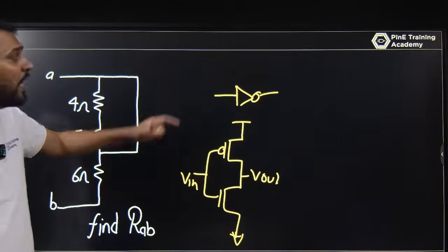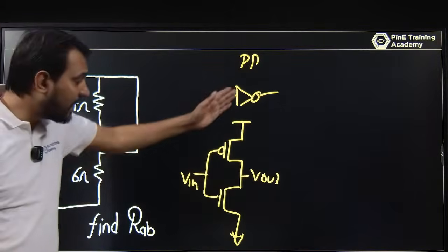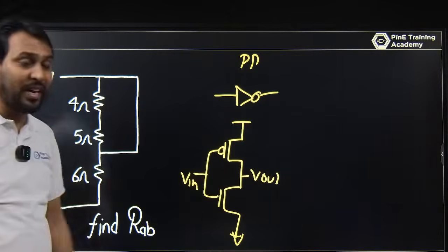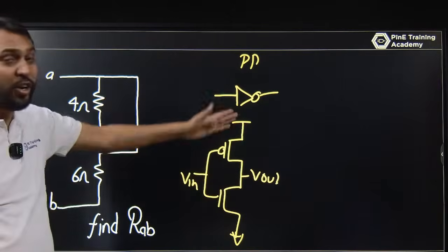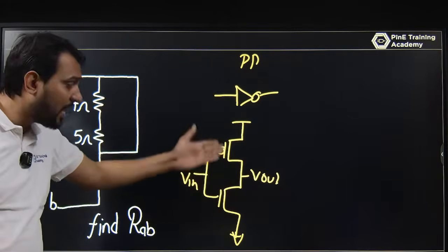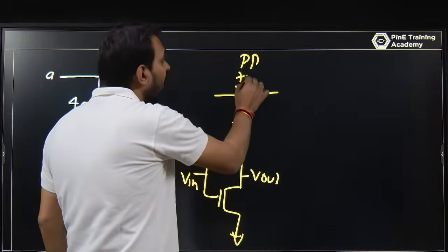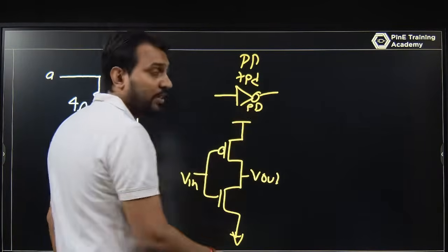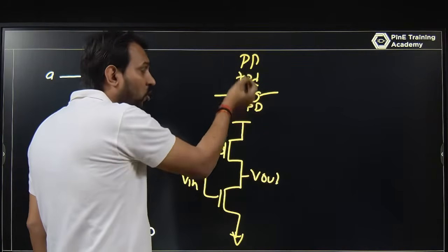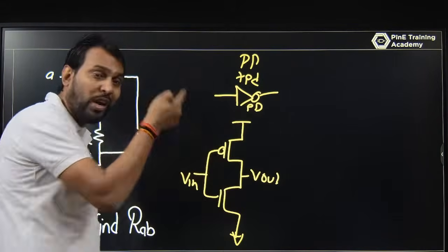Here is the difference: the PD, the physical designer, will use this symbol, and this is designed by the analog circuit designer. The standard cell team will design this CMOS inverter as per the requirement of the PD domain. The ASIC designer, the application specific integrated circuit designer, will design this CMOS inverter as per the requirement, because there is a requirement of propagation delay, of power dissipation, what will be the area, what is the threshold, what is the trip point. On the basis of the threshold, trip point, propagation delay and power dissipation, you will design this CMOS inverter.